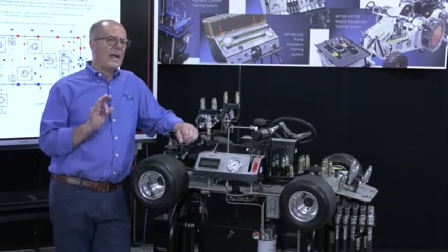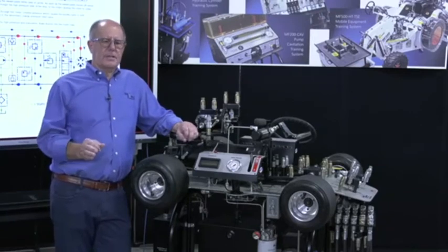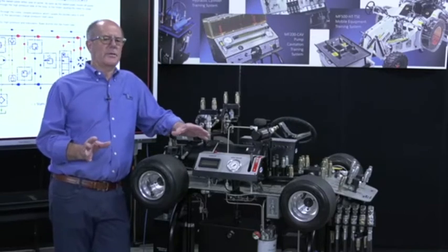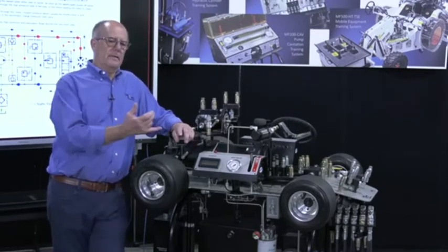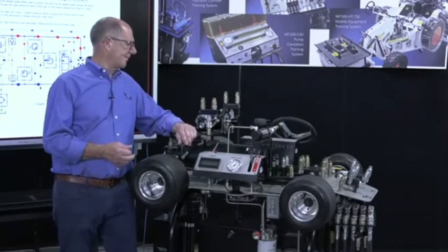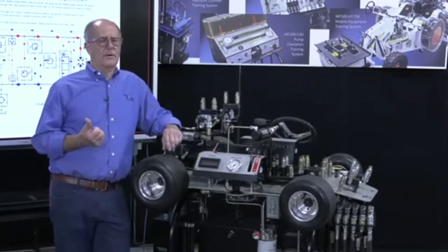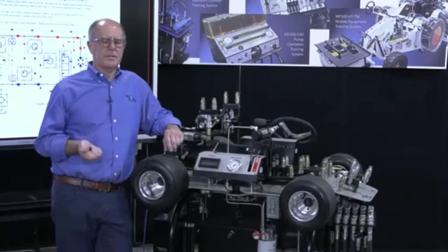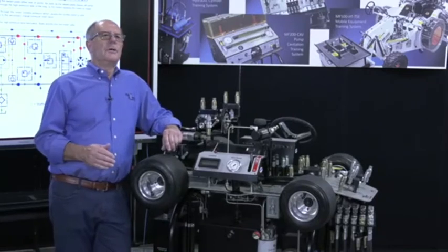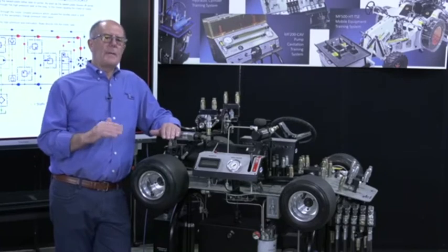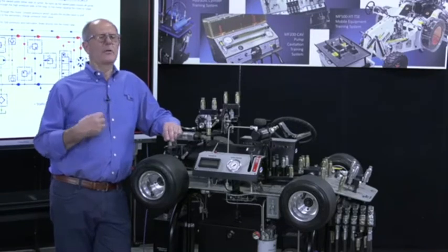So, having said that, I did a study. For 10 years, I studied leakage rates in hydraulic components due to wear. And I found that many of the components you see cannot be tested with a flow meter. You can't test a directional control valve with a conventional flow meter. You can't test pressure controls. You can't test check valves, nothing. So what I decided to do was to come up with a way to field test components using micro leaks.